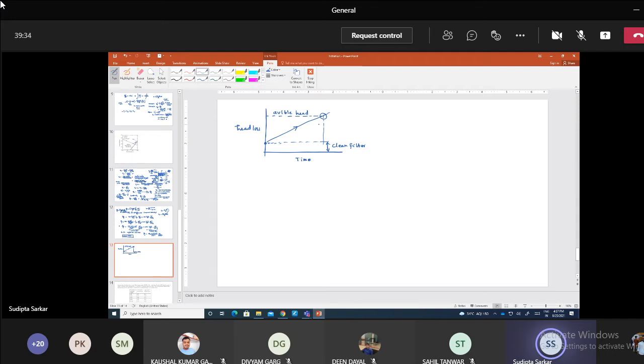This is the time we'll call THL, the time for reaching the limiting head loss. Beyond this, we won't have appreciable flow coming through the filter bed. At this time, we need to backwash the filter, as we know that backwashing cleans the filter.